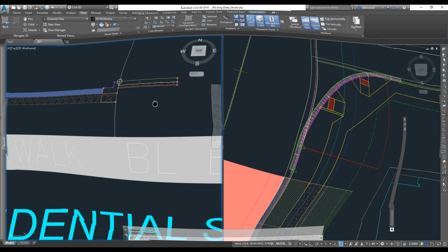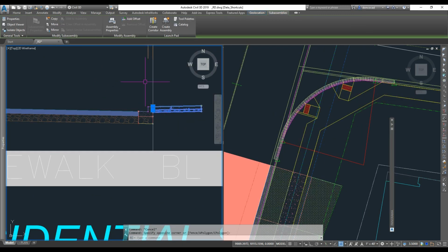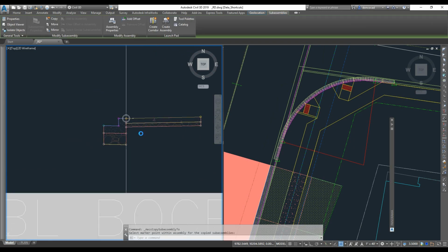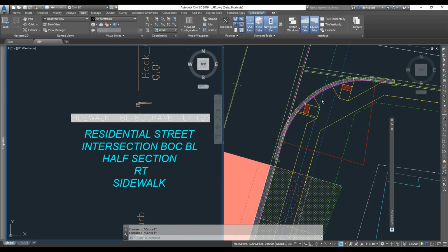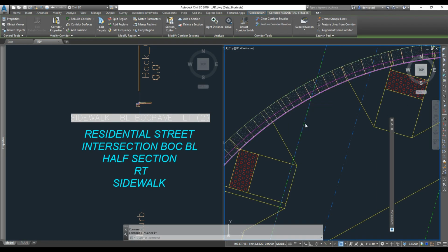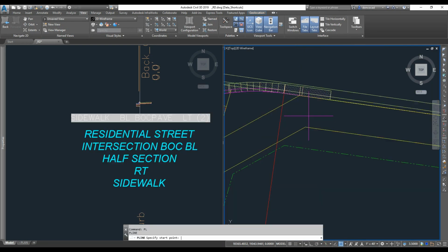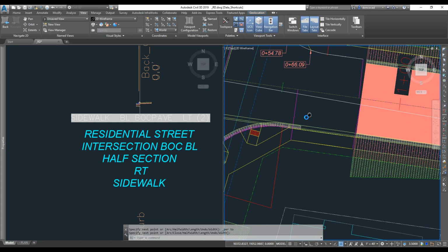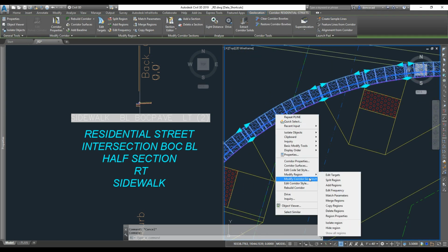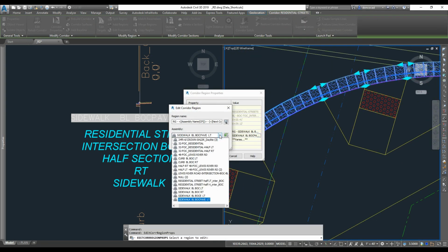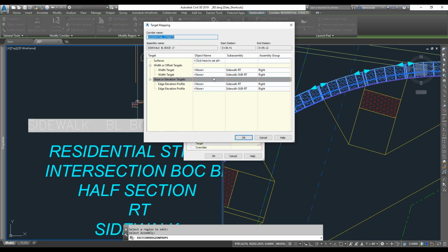All right, so my new favorite sub-assembly is the generic pavement slab, which you can use and then rename to whatever point codes you wanted to use it for, and a lot of versatility in this. So yeah, that's what I'm using. And for pavement planning, checking out my feature line grades, which I used to kind of extract from the back of walk on one corridor side to the other. That's the reason I made those partial corridors, was to get to where the back of walk and grade with those elevation line values would be near the intersection.